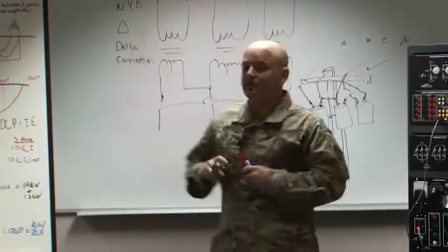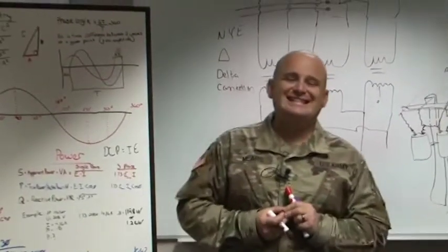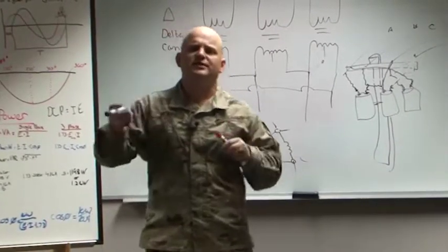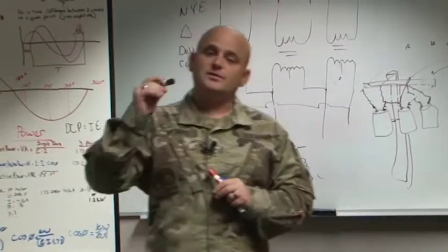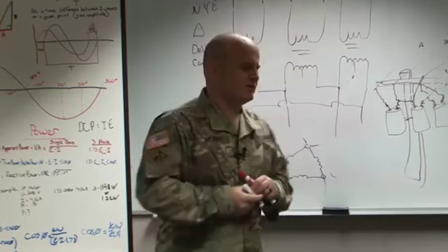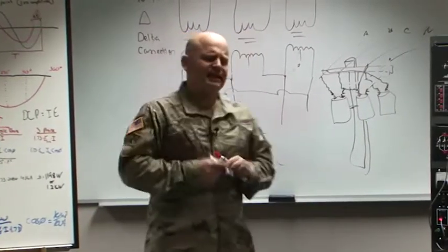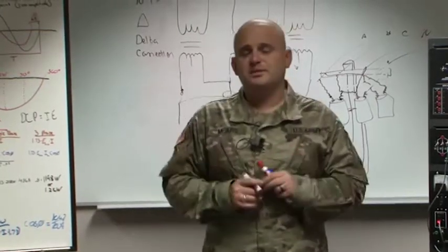Again, we're going to talk about 4 different configurations, and you're going to build 4 different circuits in the lab, and you're going to see these square root of 3 relationship differences if you're going from Y to delta, delta to Y. And it can be confusing. Honestly, it can. So just take your time and understand back to the vector references, and you should be okay. All right? And again, remember to keep it between primary and secondary and look at them independently.